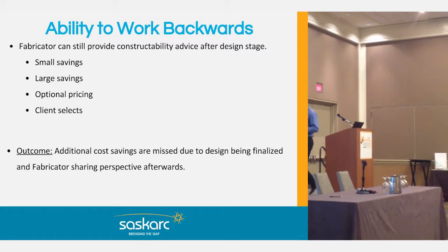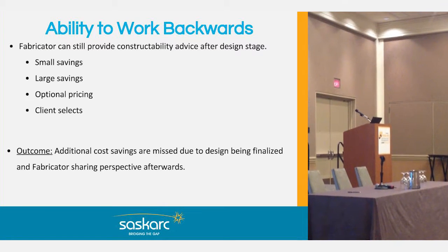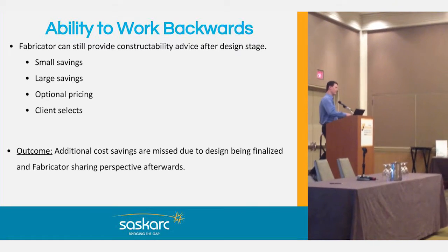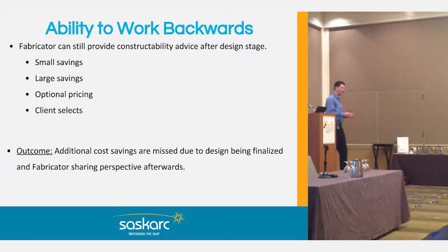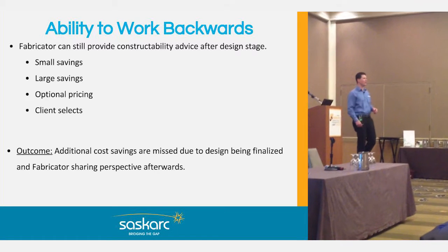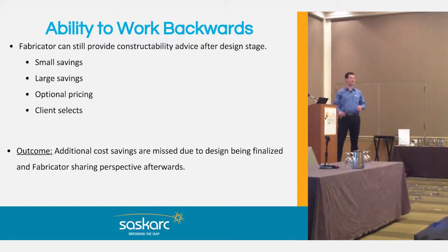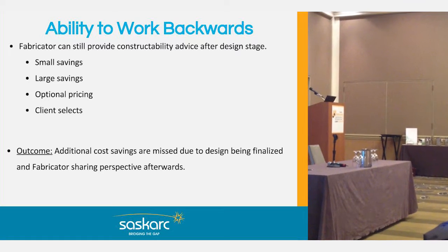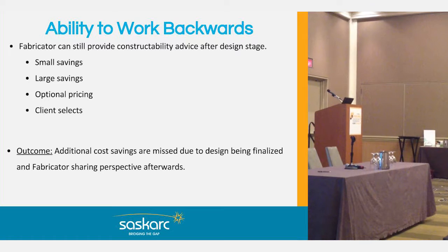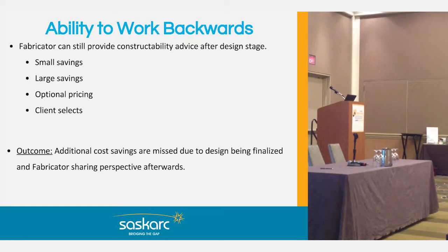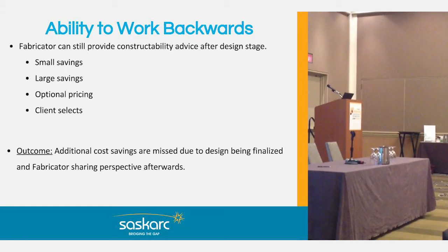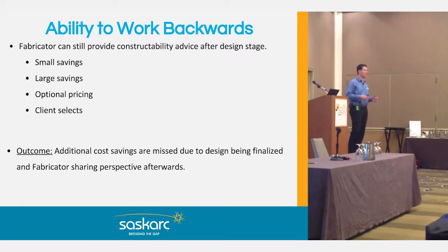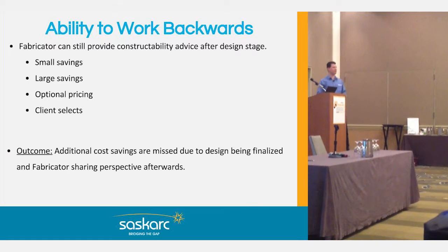And how we do it ourselves is, if there are small savings as we're going through a project that's already designed, we'll detail that in our quote and provide that back to our customers. When there are larger savings, when we get the package and review it, maybe we identify some options for modularization that weren't considered, or some material grade savings, or member sizes or anything to that extent, we'll go back to our customer and provide them some recommendations early on for their consideration.